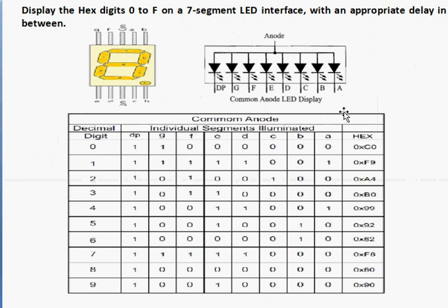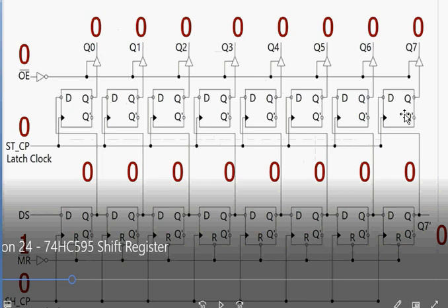So now the information you have here is 1 1 0 0. What is this? This is connected to DP. So you have DP 1 and you have G 1, and the remaining bits are all 0. So this information is sent. So definitely on the 7 segment module, you'll now be getting 0 displayed. That is achieved only when you apply a latch pulse.